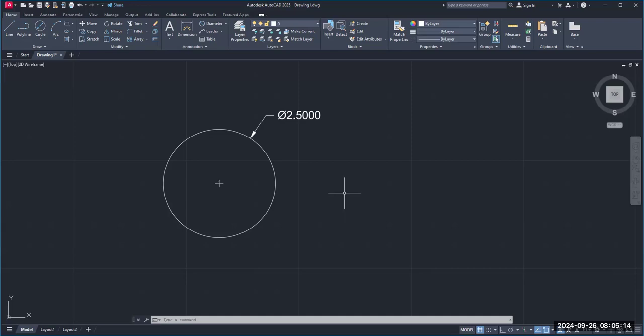Very good. Up here, the top left, by the printer button on the menu, I'm going to hit the undo because I don't want the dimension. All right, good. That's step one. We're going to make another circle now, which is our bolt hole circle, and it has a center line. Okay, it has a center line. So what we're going to do, what is the diameter of that one? What is the diameter of the actual bolt hole circle itself? Anyone? It's 1.875. All right, here's how you do it.